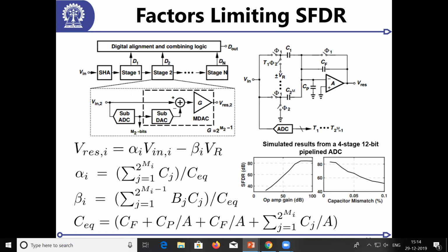So if I can add a white dither, the kind of dither that I add is up in my control. I can add random dither, white dither, low pass dither, high pass dither, any kind of dither that I want. But I should know what I am adding, and my signal processing should take care of this. So adding dithering and then averaging. Of course, once I have added dither, I have to filter out the dither. Averaging is filtering. Averaging is a low pass filter. If I average it after some time, it is a low pass filter. So this simply filters it out.